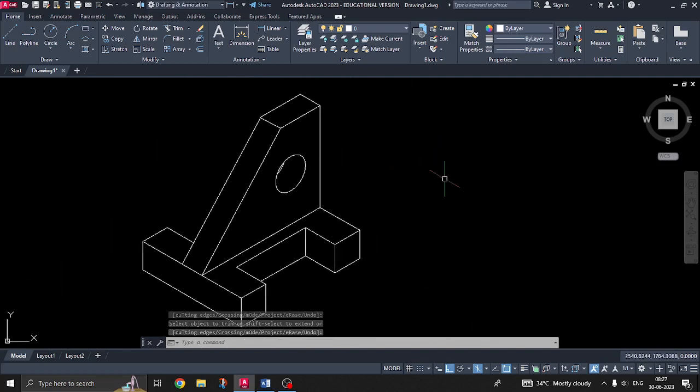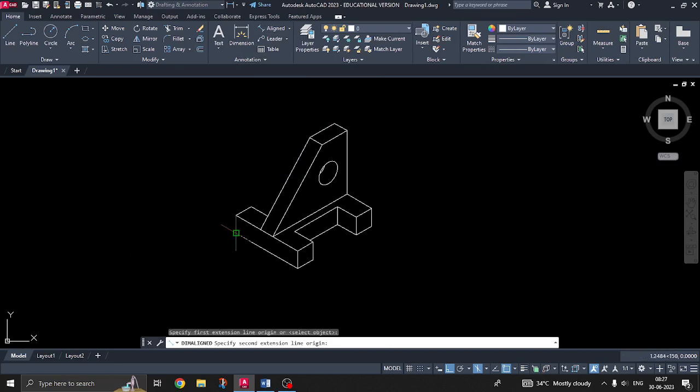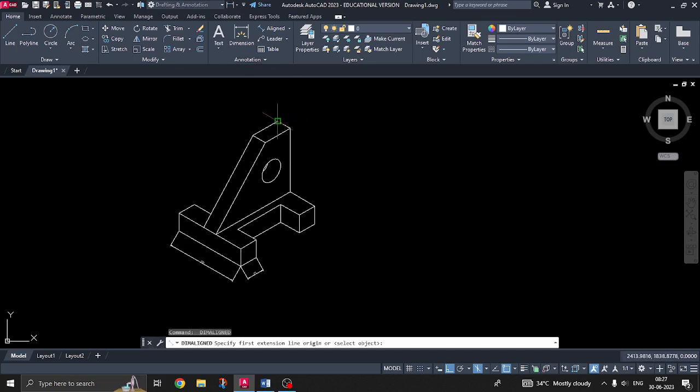Then you go for dimensioning. While giving dimension, you just give the aligned dimension wherever you want. Okay, it will come. Then thereafter we will align with that edge. Okay, aligned, select this and this, it will come. Wherever you want, you go for dimensioning. Okay, for example I am giving. Okay, from here to here. Okay, likewise this height also should be given.